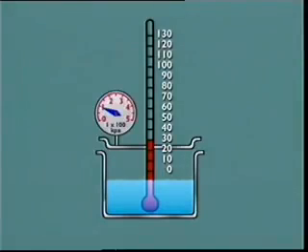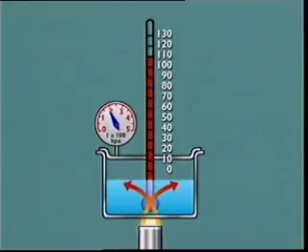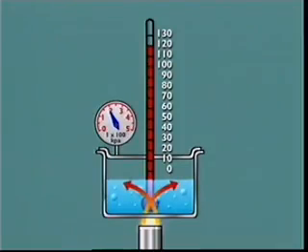If a liquid is subjected to pressure, its boiling point is raised. Therefore, a higher temperature must be achieved to make it boil and change to a gas. Subjecting water in a closed container to a pressure of 100 kilopascals above atmospheric will raise its boiling point to approximately 120 degrees Celsius. Similarly, if the pressure in the container is reduced, then the boiling point will also be reduced.